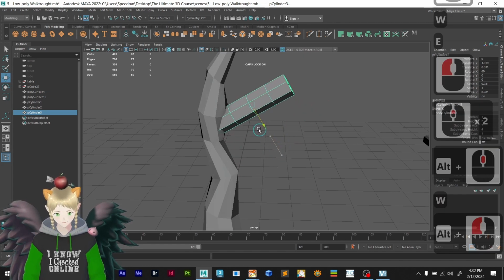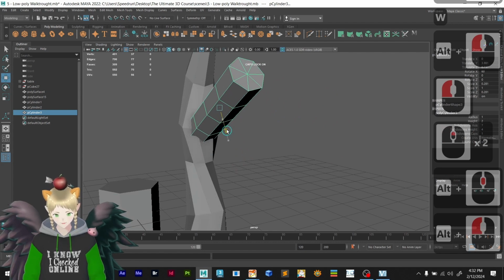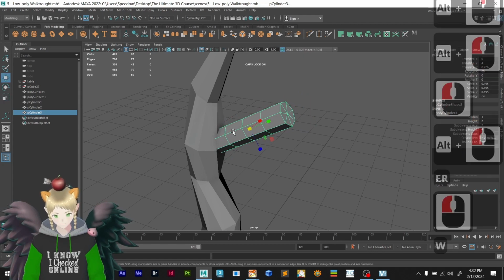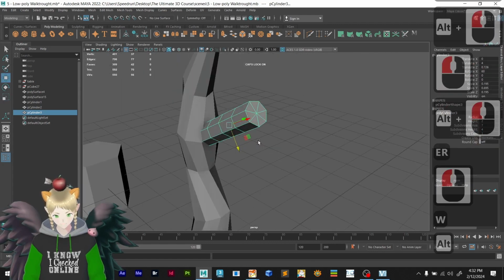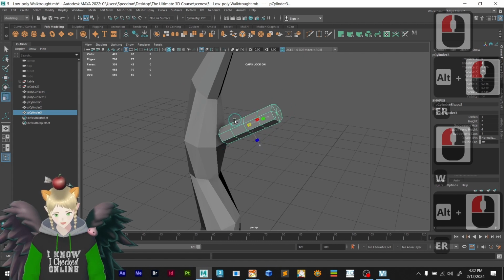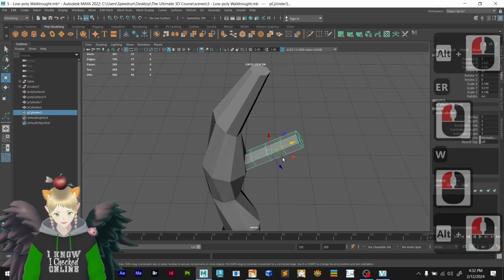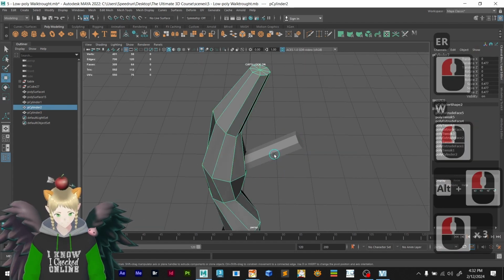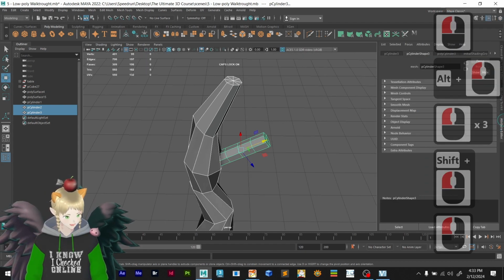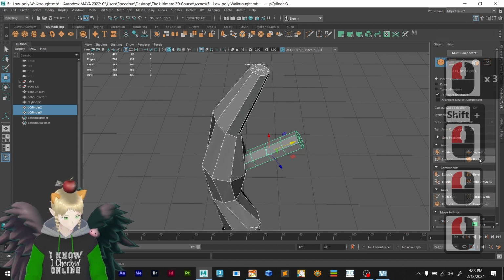I could make a separate 3 pieces here. I'm thinking to make everything from one shape, which will be very interesting for this episode. So what I'm planning to do right now is to make a little smaller here first, add this to the tree. Now I can use Boolean to remove this piece. So let's go ahead into modeling toolkit and click on Boolean.